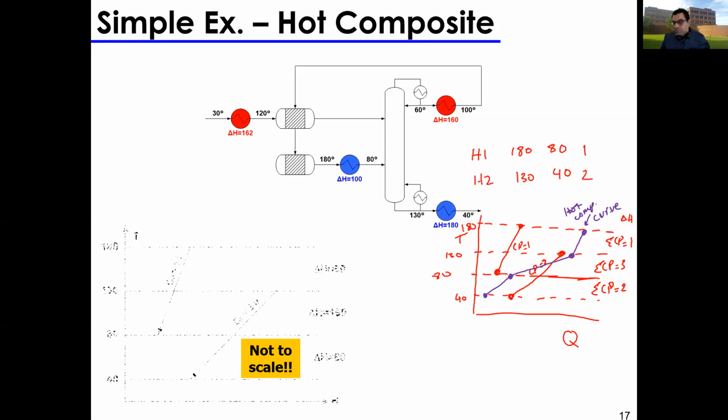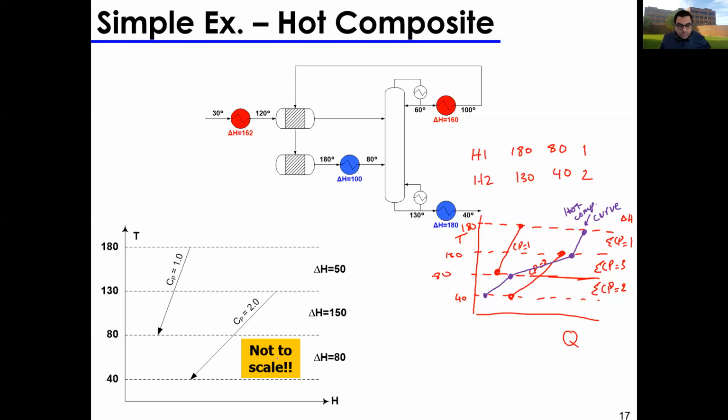And if you have a look here, so I have CP1, I basically draw dashed lines, or whichever way you want to do it. If using Excel, you can just find a way. Find all the temperatures listed in this table to form the boundaries of your temperature intervals.